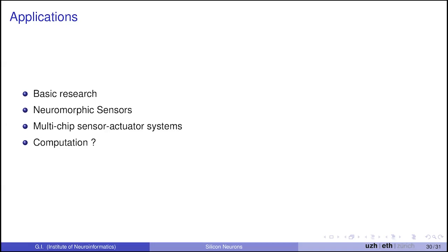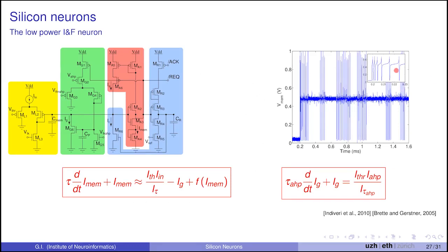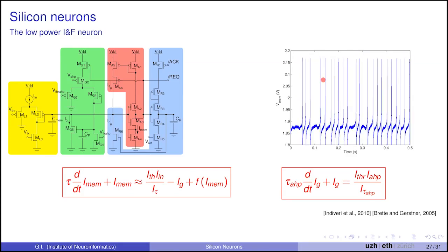Yeah, as I said, I wanted to leave some time for questions. I'm sorry that the camera batteries just ran out, and seeing how the output frequency changes depending on these parameters. Maybe there is even the chance to look at the Axon-Hillock circuit. And then if you want to get the spike frequency adaptation to work, this behavior here, where the slow variable turns on, that's an extra credit exercise where you will have to change even more parameters. Instead of switching this green block completely off, you can turn it on and then get this behavior. Otherwise, you would observe behavior of this type where you just have uniform firing rate in response to uniform current.